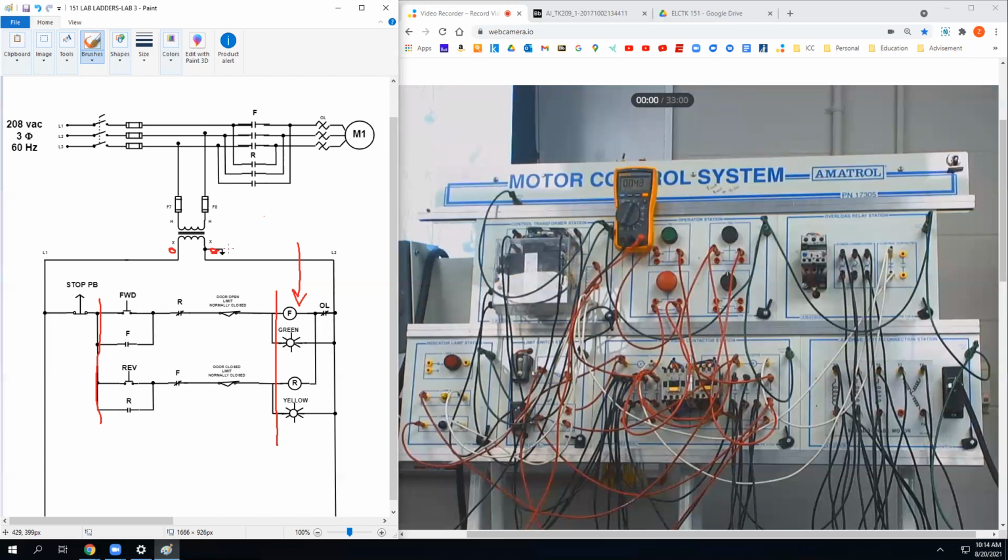I think what you're saying is right. What's happening here is, let's look at F7, if that's blown. So imagine that's open, there's no F7 there. If I check this to neutral, I get 120 volts. Then you're reading back through the transformer, you're still getting 120 volts right there, right? So just be cognizant of that. Sometimes you'll be reading things back fed through the system, which is why, when this is a problem, you isolate it and check it again, right? Because I might be reading continuity, and that's because the fuses don't have polarities, right?